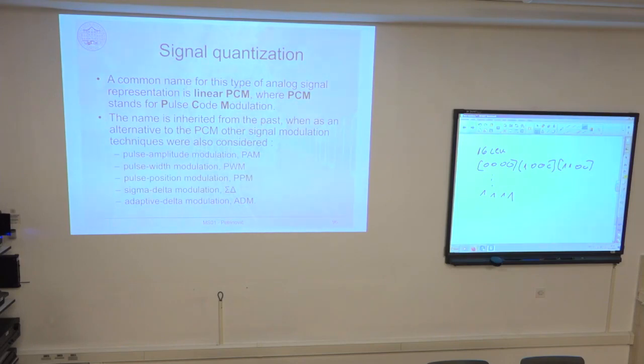If you have alternatingly changing 1 and 0, it means midpoint value 0. So if you have 50% of the time in the 1 state or the 0 state, it is exactly the midpoint, and it represents this 0 value. If it is completely in 1, it is maximum positive, completely in 0, maximum negative.